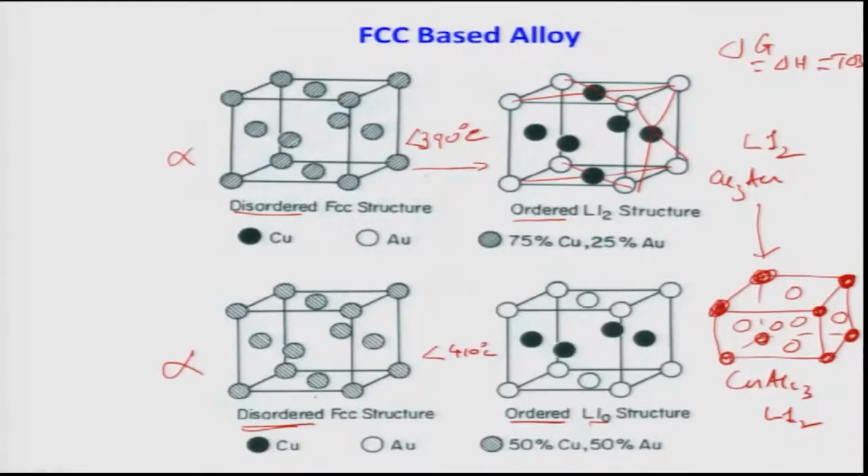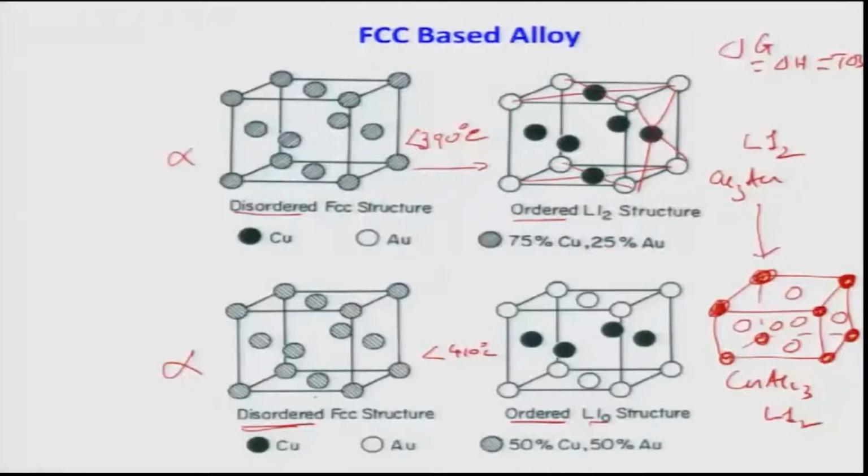One sublattice is occupied by the gold atoms, which are the corner atoms of the FCC unit cells, and the other 3 sublattices are occupied by the copper, the atoms in the face center positions. If we draw a large number of unit cells, we can connect them and get a face-centered simple cubic structure that way. So, this is nothing but 4 simple cubic sublattices: 1 gold type and the other 3 copper type sublattices. That can always be done for any structure.